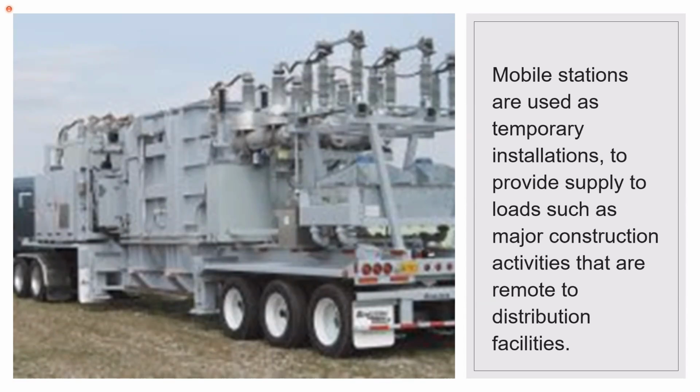Additionally, you may need to be rolling in this mobile substation. I think here in Jamaica, what we do is just roll in a transformer, really. So I recall there was a major fire out there in St. Ann recently. They just rolled in the transformer, switched from what was in the substation onto the mobile, so they could then deal with the damaged unit. And so the customers would not be out of power.